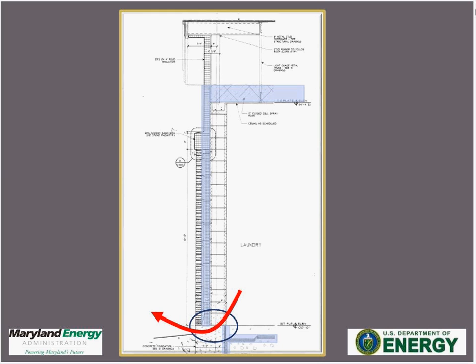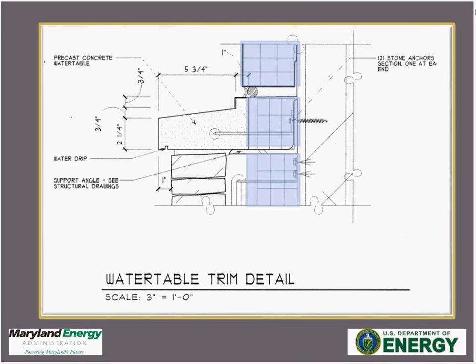The thermal envelope has a break at the foundation/slab/exterior wall junction. This is not continuous and creates a thermal bridge. Violation of C402.2.6, which details slab insulation requirements. In this detail, these types of thermal breaks are so small they are unavoidable and are relatively insignificant.